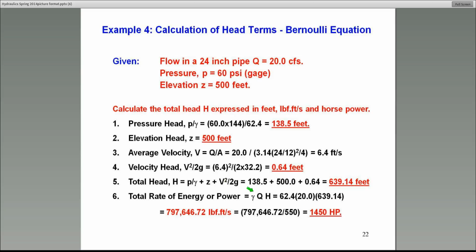also be doubled. That should tell you something because in turbines, when you run turbines where you generate power, it's a function of both the amount of head that's available to you as well as the flow rate that is going through the system. Gamma, of course, you can't do much with that other than change the fluid. But right now with water, it's 62.4.